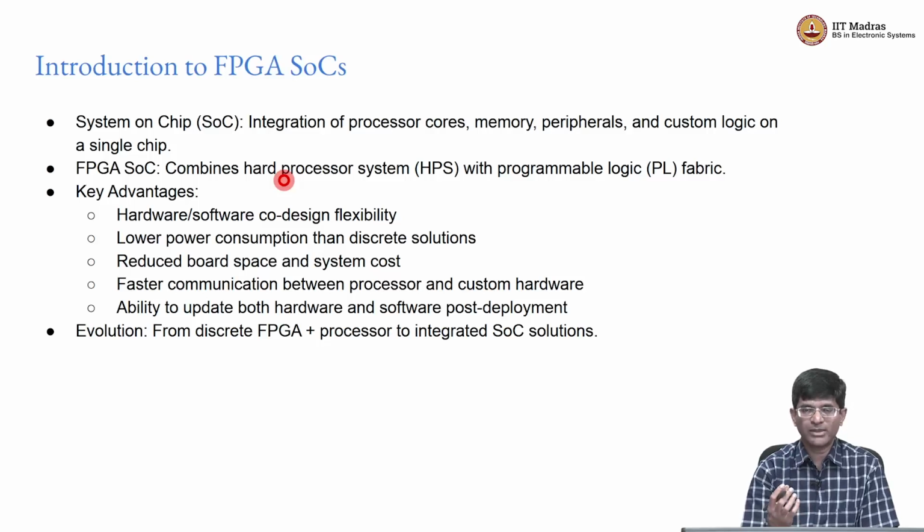It is not a soft macro in the sense that it's not given to you as a piece of Verilog or VHDL code that can get synthesized and put on the FPGA. There is actually a so-called hard IP. There is a block sitting on the silicon that can only perform this SoC functionality and cannot be reprogrammed as such to do something else. Okay, so that is the sense in which this word hard is used over here.